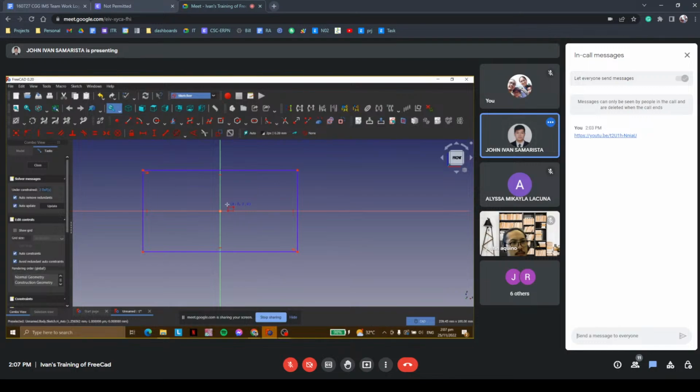But if you're just making a simple object, or let's say a single object, this is fine. But when you're dealing with an assembly with different parts, and considering that you have to make such changes at the end, it's very important to consider this origin point. If you want our object to be adjusted in the assembly using the spreadsheet, we need to set our origin point at the corner of the object, or let's say at the far end of the object.